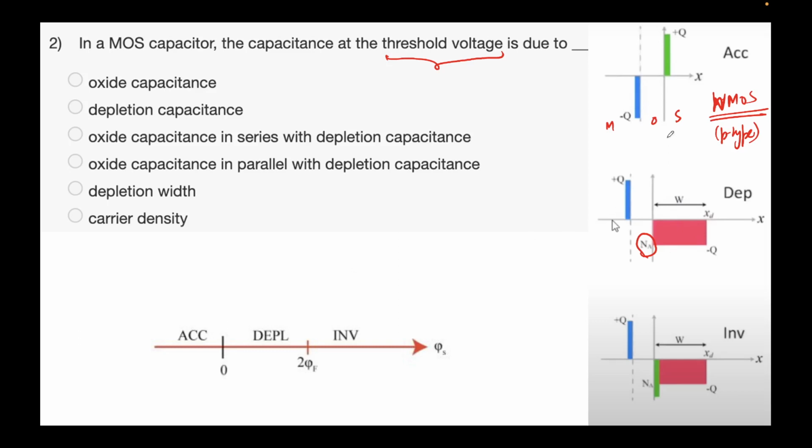And if you want to denote the same charge story in terms of potential, here we have phi s. We saw in the last class something called the surface potential, which we defined as the Ei at surface. This interface is sometimes referred to as surface. Please note that when I say surface, I mean this, not this. Please just be careful. The metal oxide interface is what I'm calling the surface. Phi s is Ei surface minus Ei bulk. This is the definition.